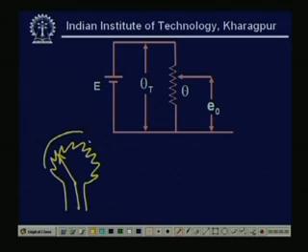So, you see here the total rotation is theta t. I can have any position theta. I am giving the battery voltage here. So, this is my E, and I can measure the voltage between this point and this point, that will be my output voltage E naught. So, total is theta t. This gives the schematic view of a potentiometer.